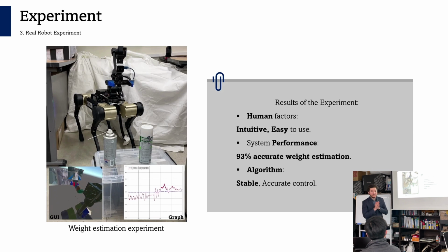I implemented end effector velocity control as well in the first place, when I was planning this motion control. This is the D gain for velocity compensation, task space damping, controlling the end effector velocity. So not only joint space D, I implemented task space D as well in the first place. But I removed it. I didn't put it in the block diagram. The reason for that was